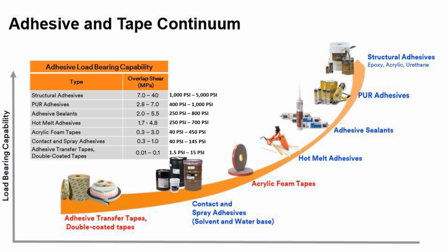As you move up the continuum, contact spray adhesives, you add a little more strength. Once you start hitting acrylic foam tapes and hot melt adhesives, you gain even more. Adhesive sealants, PUR adhesives, and structural adhesives are going to give you your greatest strength on this continuum.